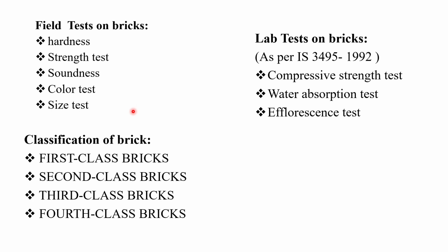The third one is the soundness test. In the soundness test, we will stack two bricks to each other, and during this procedure, the brick should not break down, and a clear metallic ringing sound should be audible. So this is the procedure for the soundness test.